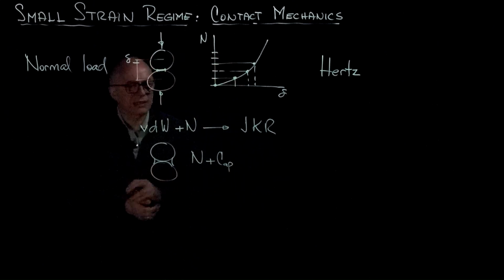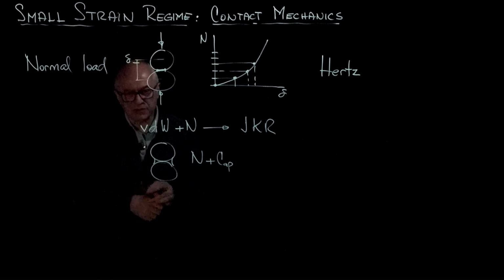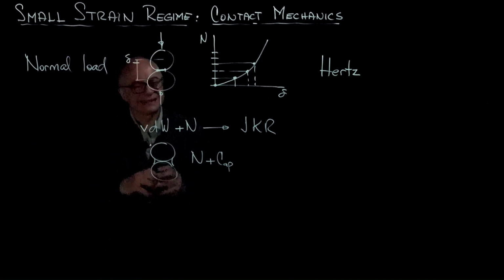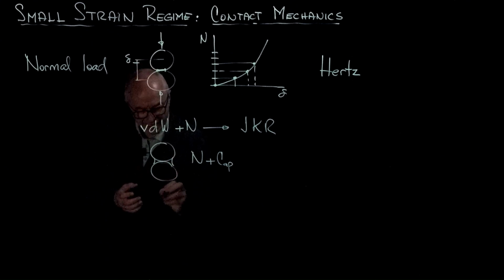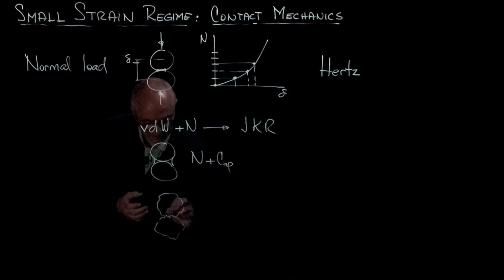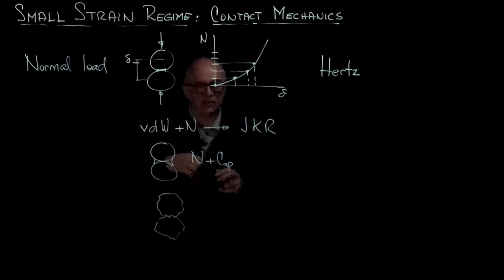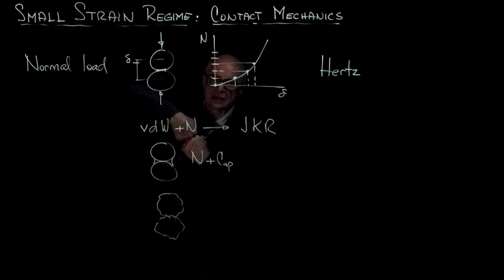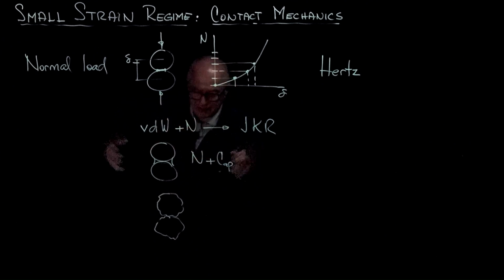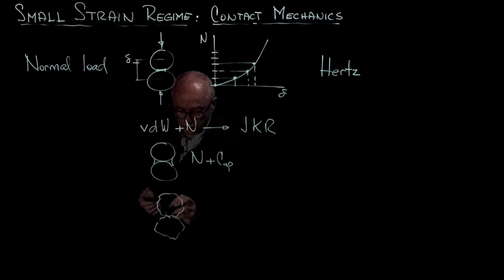Another situation that may emerge is that particles are not necessarily smooth spheres, and the particles have some roughness. And in this case, we need to recognize that the deformations will localize at the asperity contact. So there is both a significant deformation of asperities, plus these asperities are also going to force a pronounced deformation near the contact by stress concentration.